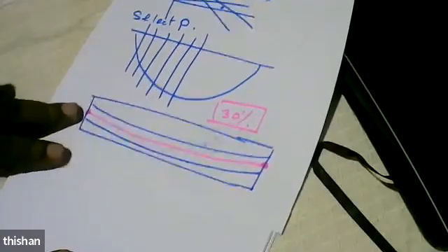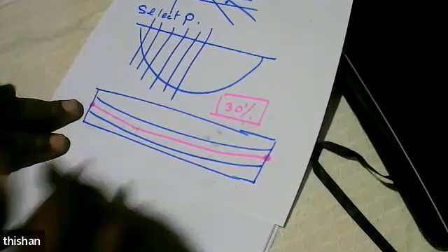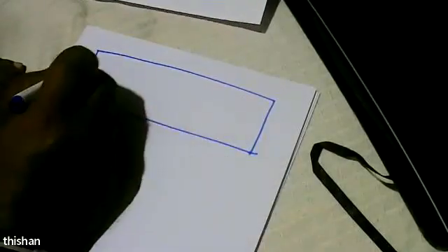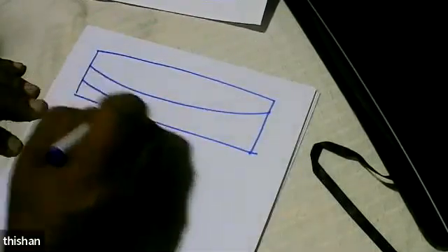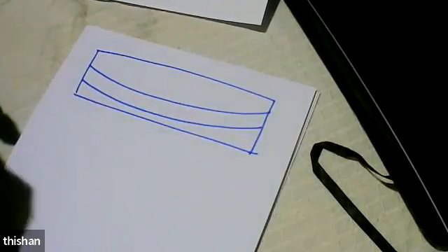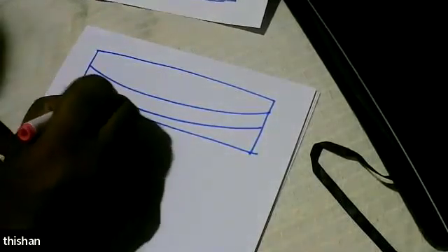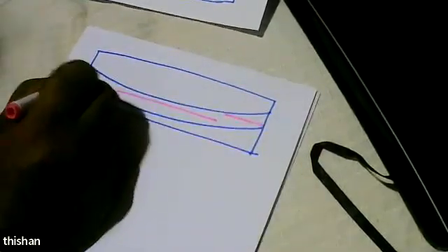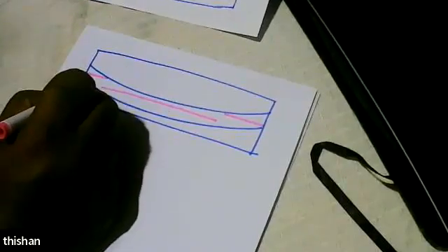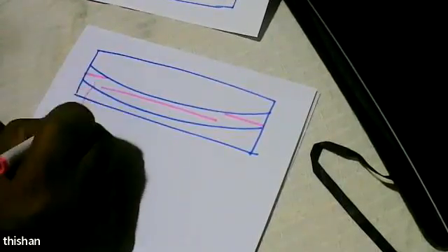But then we also can have another option. We say we are not going to go for post-tensioning, we are going to go for pre-tensioning, and we might have a cable like this, a straight cable, and another cable like that, and here we shift the centroid by debonding.